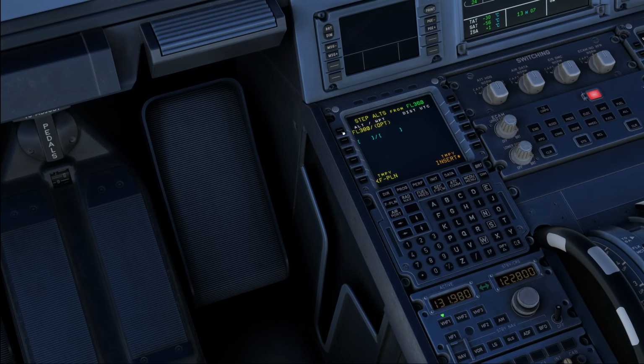So if you only enter the altitude like here, it's going to calculate the optimum waypoint. This takes a little bit, and then you are going to get your distance and time to the optimum waypoint, and down here it's going to tell you how much fuel you are going to save. I'm not 100% sure if that is actually simulated in the Phoenix Airbus, but generally this is what we would do in order to calculate our step climbs.